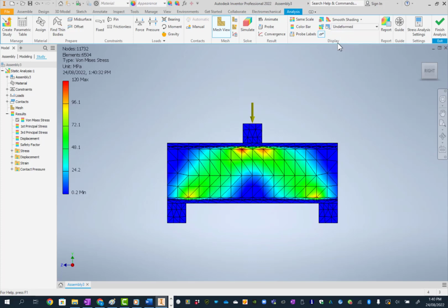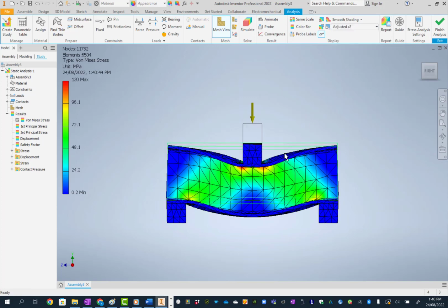If I look at it undeformed, so with no deformation at all, it's not showing any deformations. You can see I've got little rectangles here. There's a triangle in the middle, ignore that. But if I now exaggerate the deformations, you can see that those are turning into little parallelograms. They no longer have square corners. They're not at 90 degrees anymore. And that tells you that the shear is high through this area.